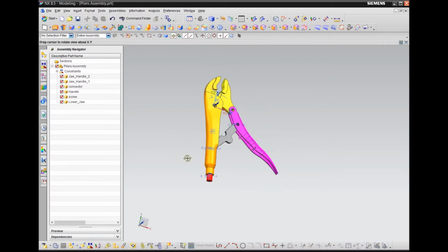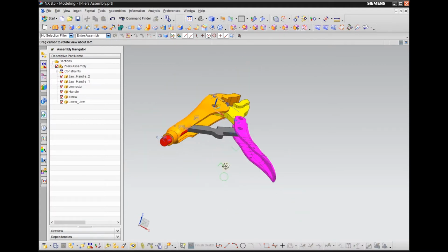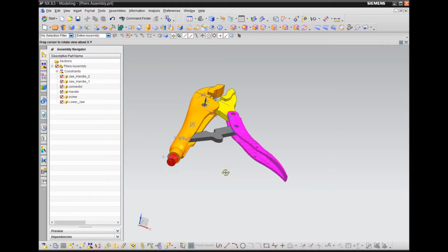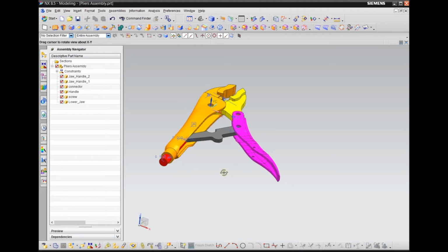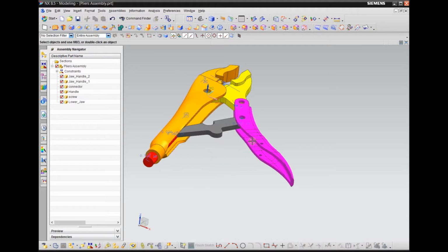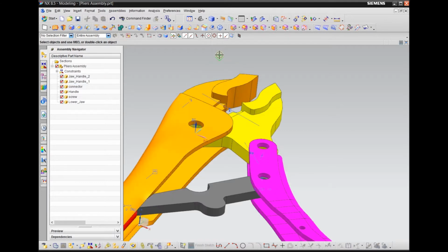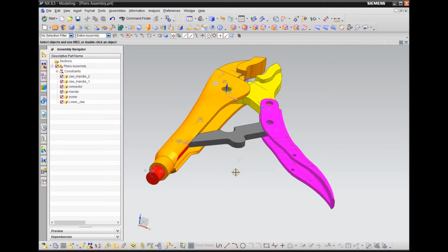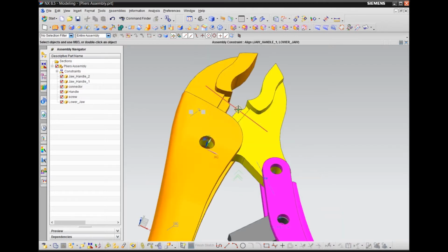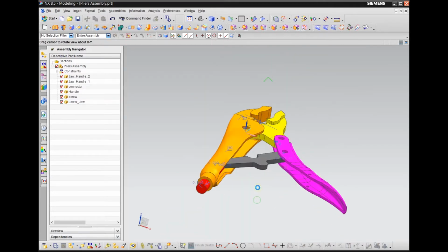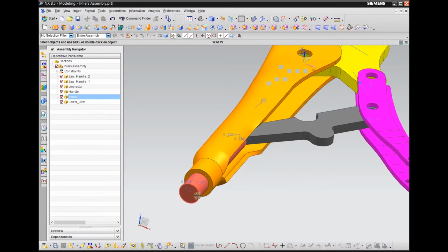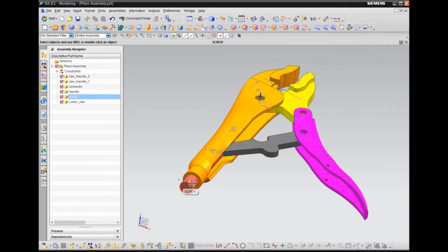That's the CAD model we modified, optimized for the simulation. So we removed the grips, and we removed the trigger, which is not used in this simulation, and we deleted some tiny features like the teeth and the chamfer here. It's also deleted, and we idealized the screw.